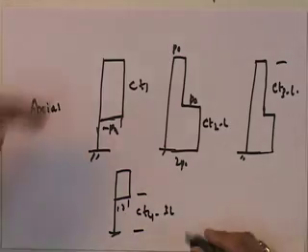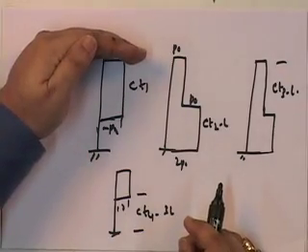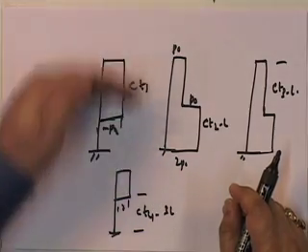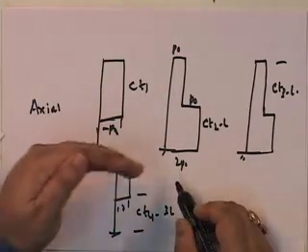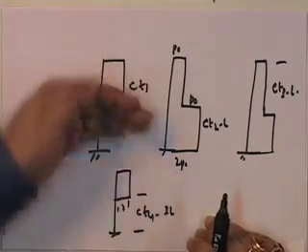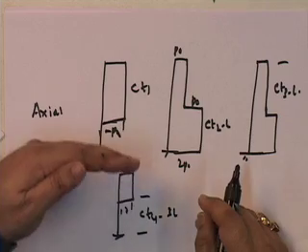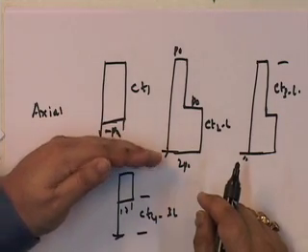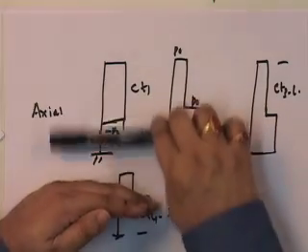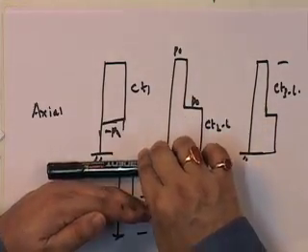So, you have the load P naught suddenly applied here. That sets up an axial force wave which comes here, and as it hits here, it gets reflected. Since it's a rigid boundary, the stress wave comes over here and is reflected back.